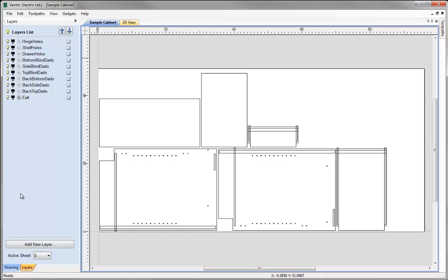And these layers that you can see on screen at the moment have actually been imported along with the vectors which come in a DXF format from this cabinet maker's design package, and it has actually retained that layer information. And so any further cabinets that I decide to make in the future on this particular software, when I come to import them in, we will have the same layer information and hopefully the same vectors relating to that, so that when we do actually utilise the toolpath template, it's going to look straight away for the particular vectors that we're going to specify on that particular layer, then apply the toolpath to them, which in the long run will save us quite a lot of time.